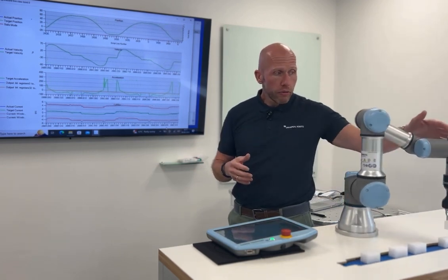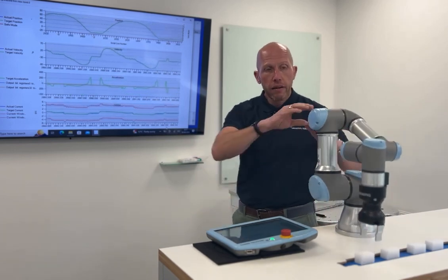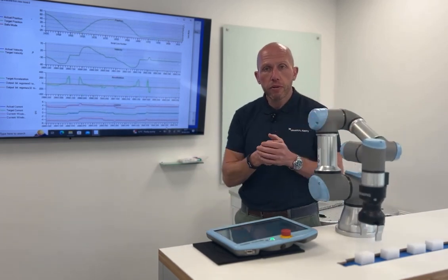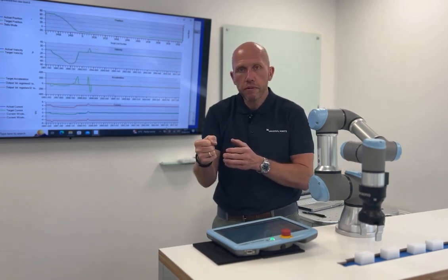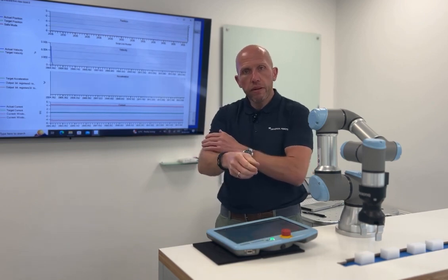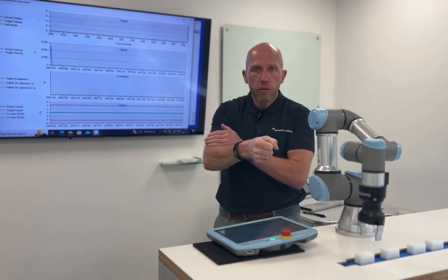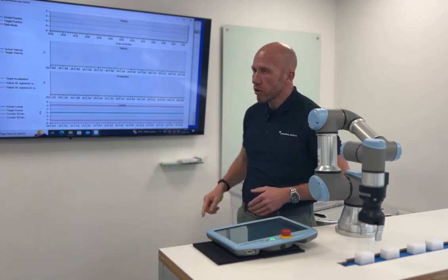Or sometimes we see it on palletizing applications where the dress pack of the pneumatic pipes are maybe too tight, so when the robot's trying to move, the actual dress pack's restricting it. Also in welding, the umbilical for the power pack is actually holding the robot back, so we can start to see that spike in the actual joint graphs itself.